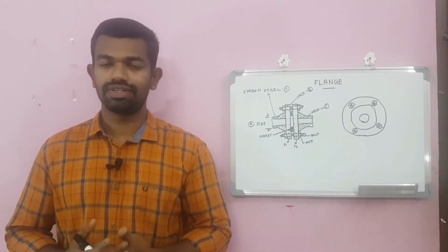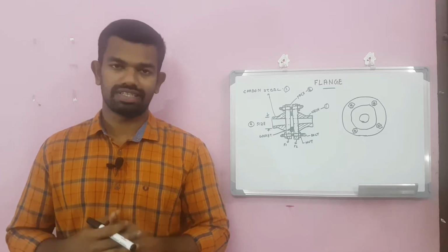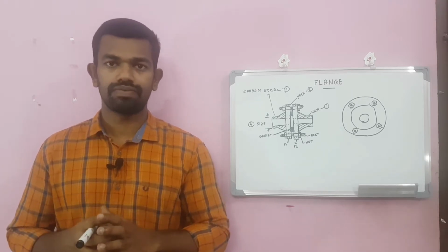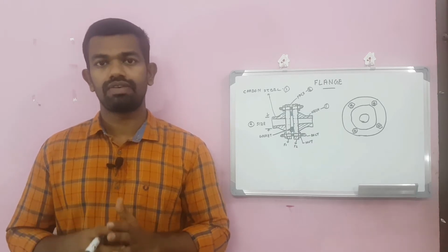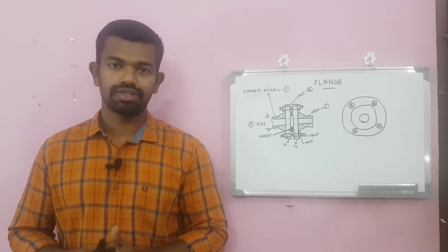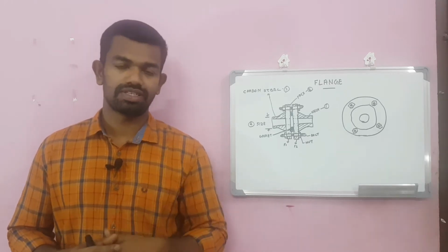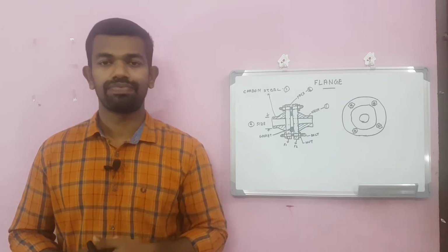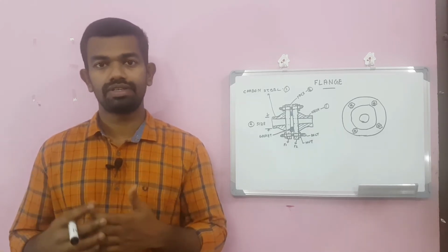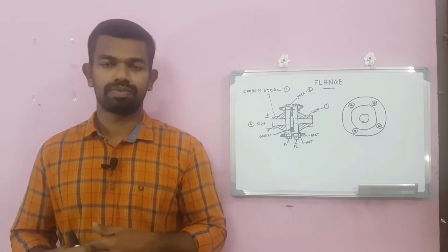A flange joint makes it easy to connect, disconnect or dismantle equipment, piping components, or a nozzle with an instrument, or for isolation purposes, or for connecting and disconnecting piping components such as strainers, valves, etc. This is called a flange. It makes our job easy for connecting or disconnecting, including for maintenance purposes.